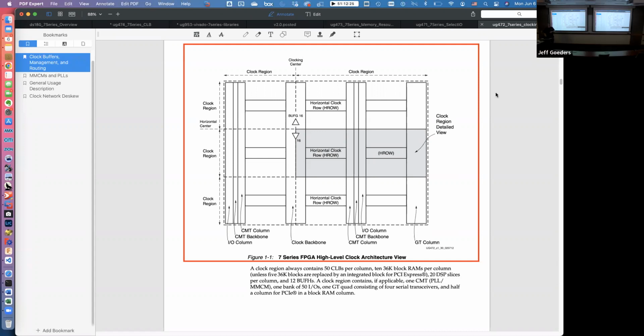And so hidden from us is a huge infrastructure that can have like 16 clocks all running around at different frequencies, but every wire length and every driver has been carefully calibrated to get every flip-flop in the entire circuit to get the clock edge as close to the same instant in time as possible. And if you ever run a detailed timing report, they will build in a little thing called clock skew or jitter. And that is the uncertainty of when various flip-flops receive their clock.